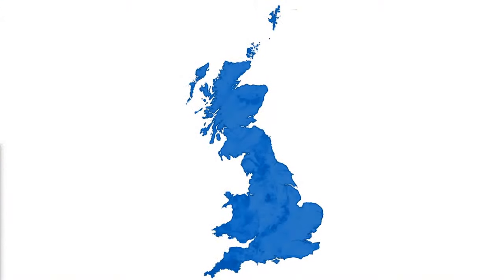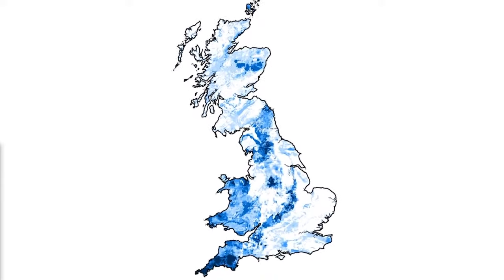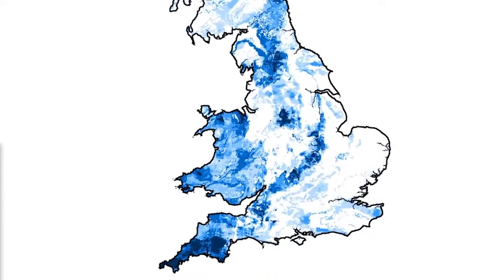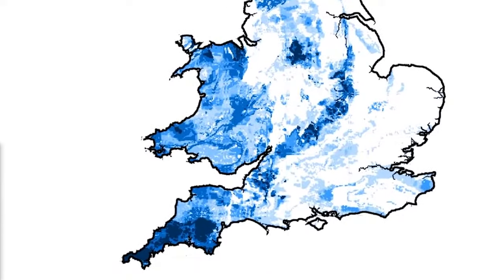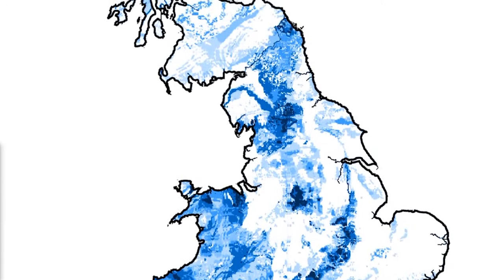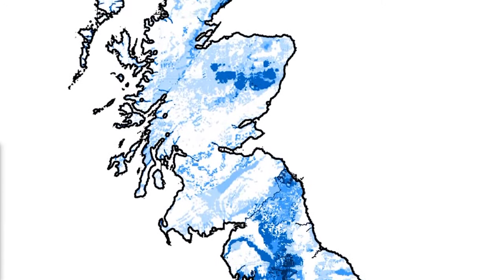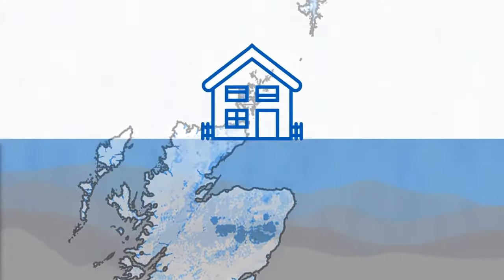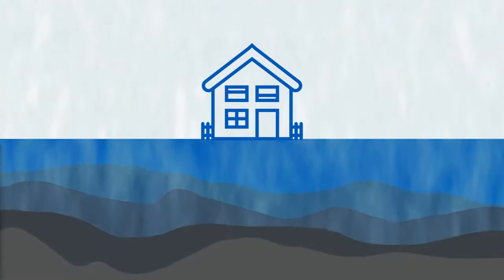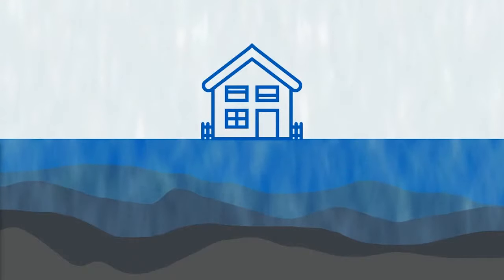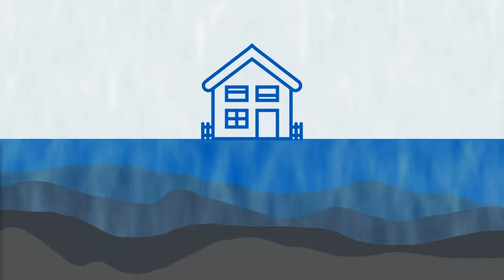Radon is a little different in that it's associated with underlying site geology rather than historical usage. The necessity of testing for radon is therefore determined by radon maps, which detail where in the country radon-releasing geology is likely to be present. Once the contaminants are identified and the associated risk quantified, remedial measures can be specified.